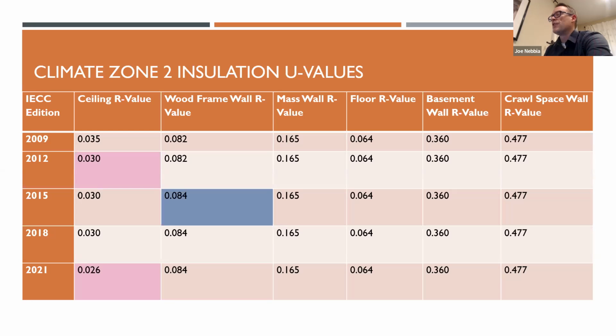Then they have to go for the U value target rather than that R value target, because it's a continuous insulation at that point and it's not interrupted by framing. Likewise, if you're going for a framed wall and you have some other combination, the example I used before was an R11 plus 3, where R11 is in the cavity and R3 is on the outside. You could do that U factor calculation and comply with the code in that way.